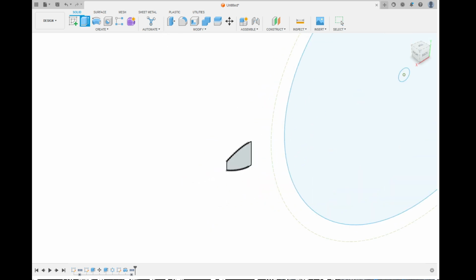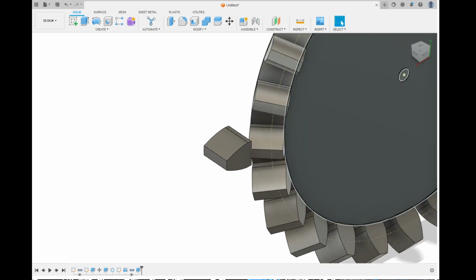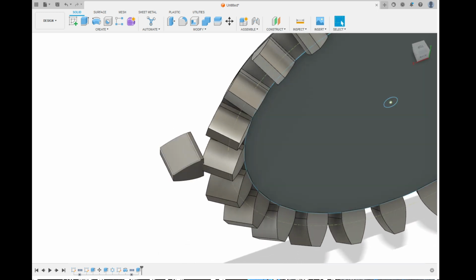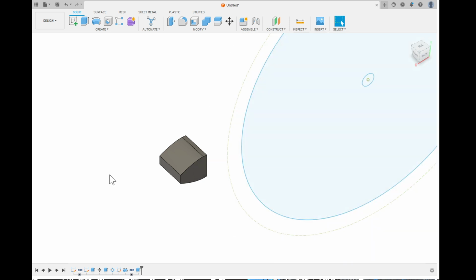Extrude this. This time, just to save time, I'm going to extrude this to the whole 30 millimeters before. If I press OK, where did that go? Went over there. So if this is the main gear, I will make the copies first and then we'll rotate it. Because while we still have the circle for us to base this copy around, we're going to go to create. Now, I don't think you can see these tables as well, but under create, if you press the arrow down, pattern, circular pattern. Oh, sorry, before we do that, we need to angle this at 45 degrees.